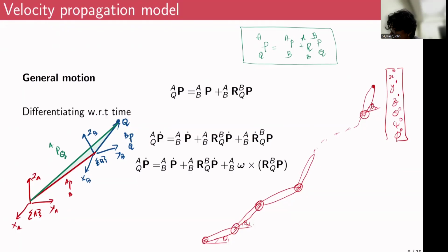So here you can actually see that each and every joint would contribute to the velocity in task space. For example, in a very simple case, if you have a 2R robot like so, with this being theta 1 and this being theta 2, if you rotate theta 1 alone while keeping theta 2 fixed, you will have corresponding linear velocities x dot and y dot.